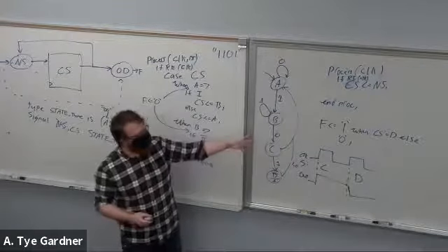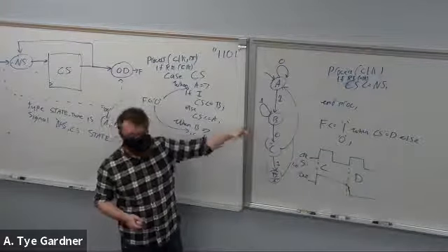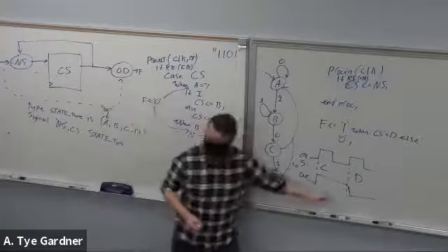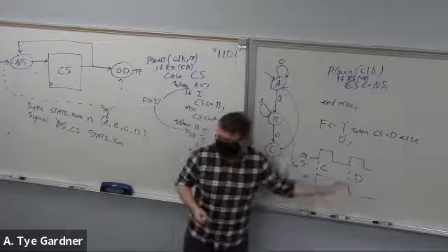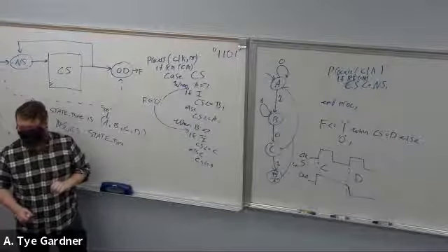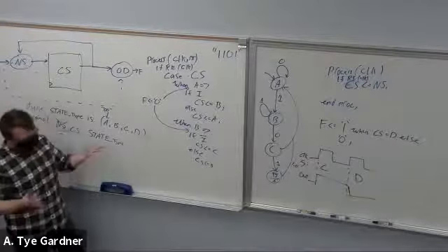You can actually change the output decoder to have a process and a clock on it. If you want to delay this by 1, you can just add a flip-flop to that. But you would have to copy and paste your outputs a whole bunch to make that work. Again, it would probably work if you didn't do that, but it's not something that I want to gamble on at all.